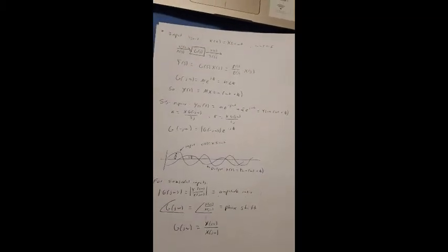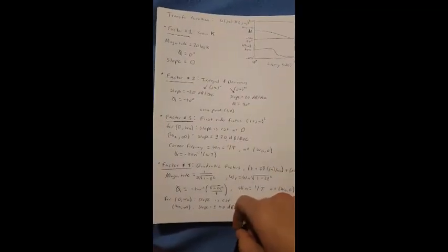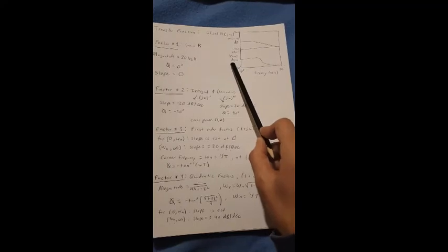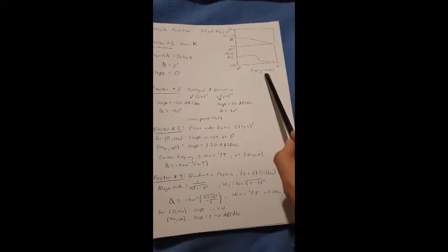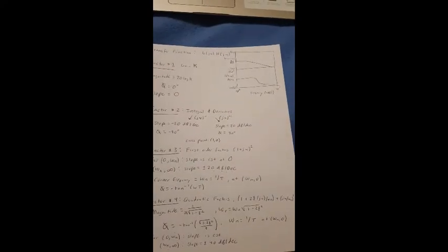Three commonly used representations of the sinusoidal transfer function will be discussed later on, including the Bode diagram, Nyquist plot, and the Nichols plot. Now we will begin with the Bode diagram. It consists of two plots over each other, the first one being logarithmic magnitude in dB, and the second one being the phase angle or shift versus the frequency. The advantage of this is that we can analyze the characteristics at low frequencies as well.